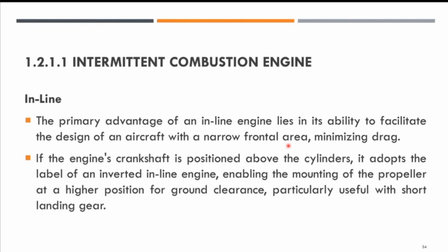You do not want the engine to be very bulky, because it will of course have a broader frontal area. If the engine's crankshaft is positioned above the cylinders, it is labeled an inverted inline engine, enabling the mounting of the propeller at a higher position for ground clearance. This is particularly useful with short landing gear.